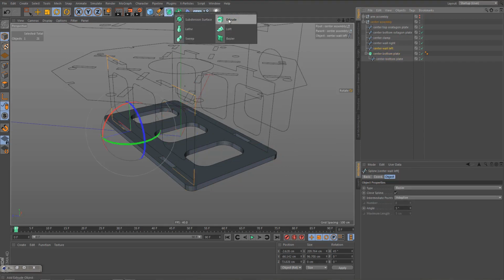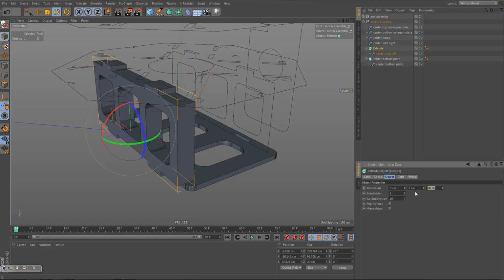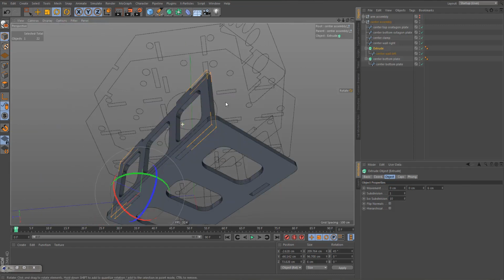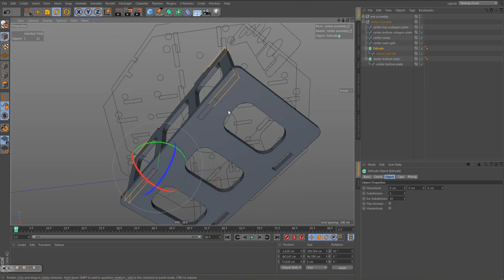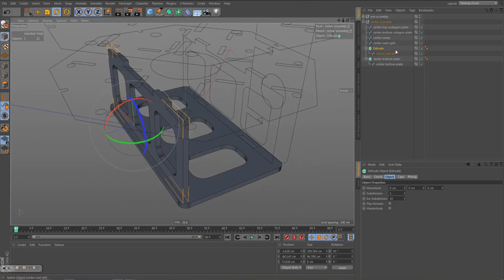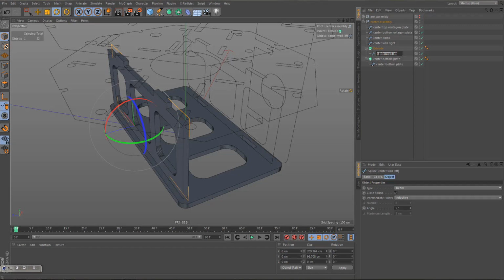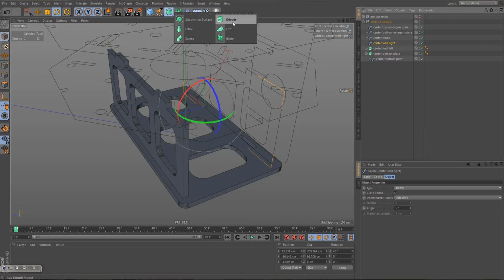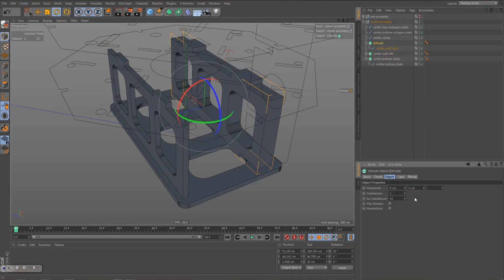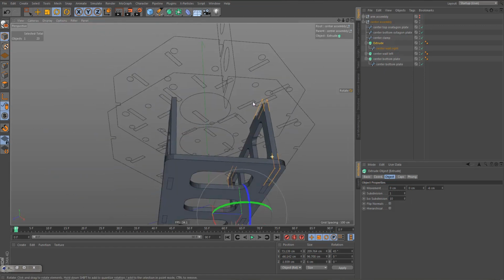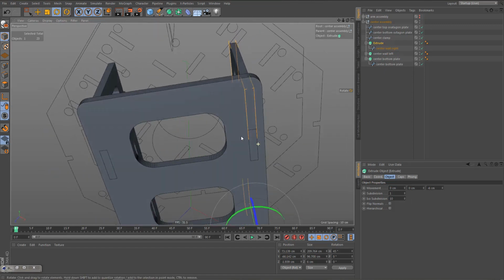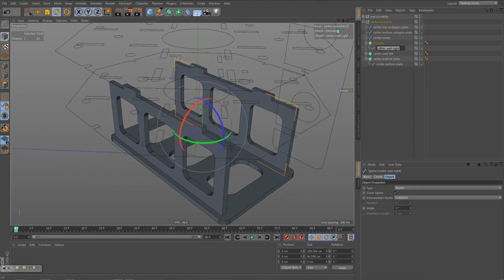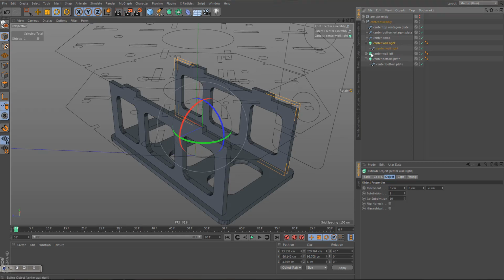Let's continue with the left wall, and we need to extrude these, or this wall, 6 centimeters, and you can see this is fitting perfectly. I'll rename this and extrude the other wall, and here we need to do -6 centimeters. And that's a perfect fit as well.